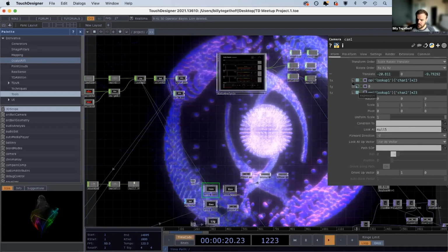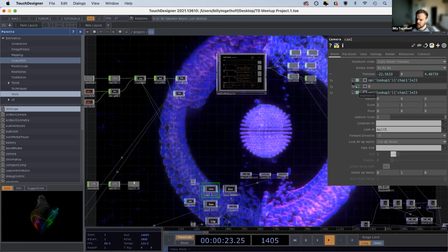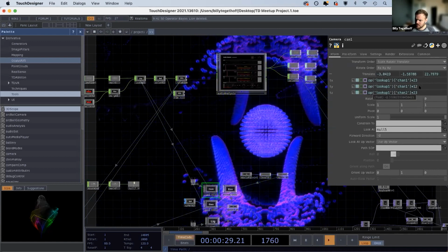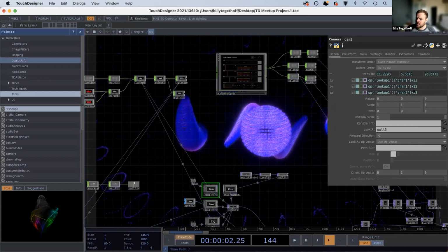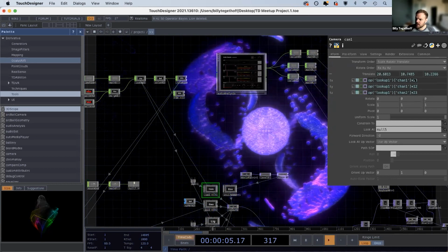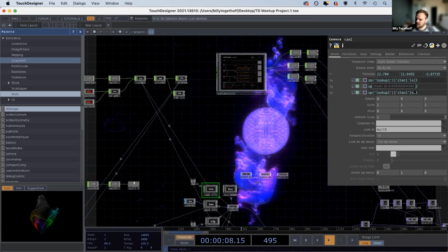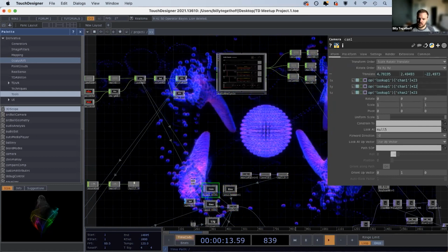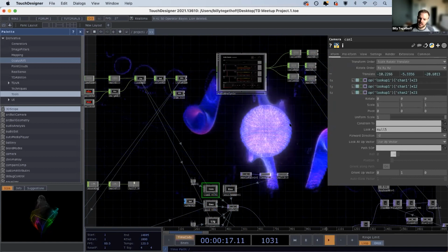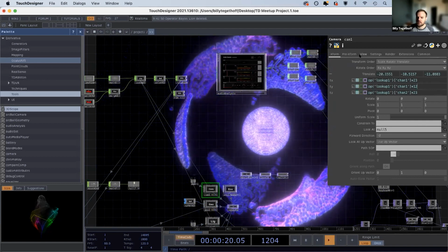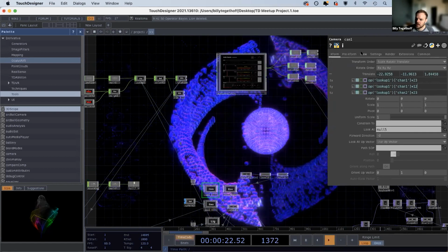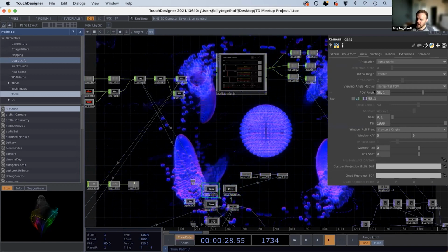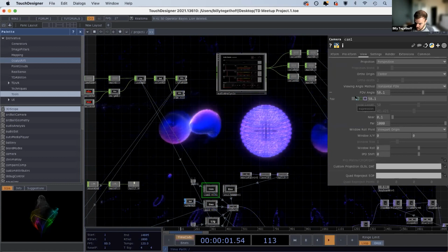So one of the things I like to do to just spice it up and make it a little more interesting is add something in my Y translate value. This is of course to taste, but typically I like to have whatever distance is applied to my X and, I'm sorry, my X and Z, somewhere in the neighborhood of half of that in my Y. And then you just get some kind of gentle up and down as the animation progresses. The other thing that I like to do to make it a little more interesting without having to do anything like manual keyframing is I like to animate my FOV angle.